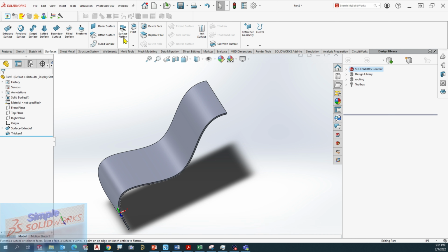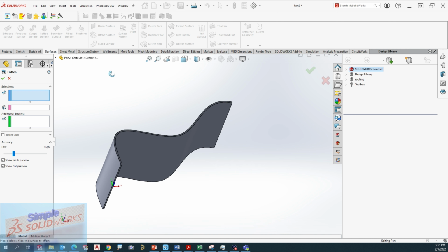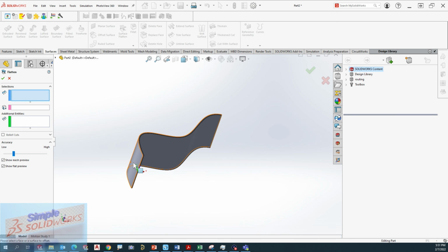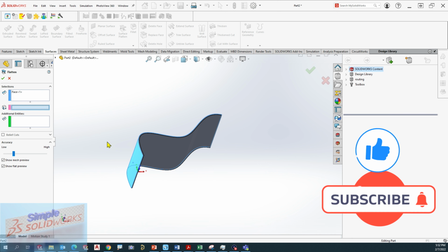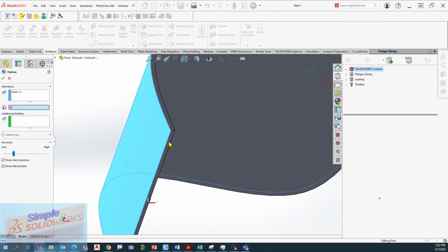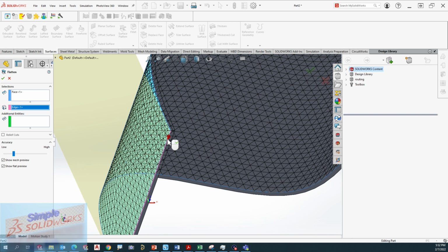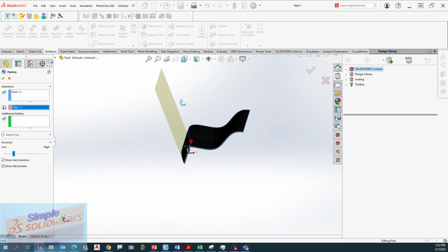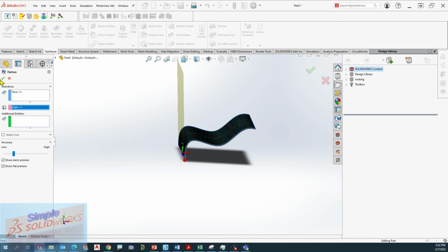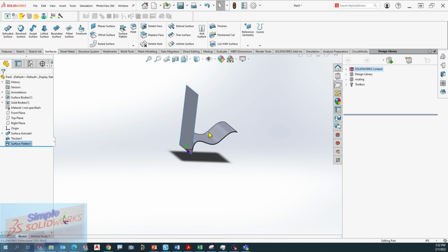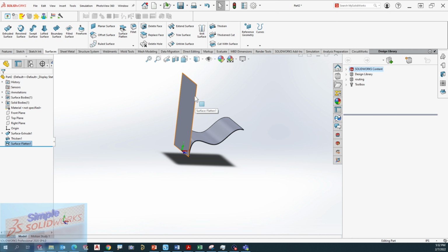Then you're like, well, where is it? So if you click on that, it's going to ask you to pick what you want to flatten. Then you say I want to flatten this, and then you say, okay, but I want you to hold it from this point and flatten everything else, and it'll give you a nice flat pattern. This is good in case you don't know the measurement of this, but you want to know what you've got to cut at a laser, right?